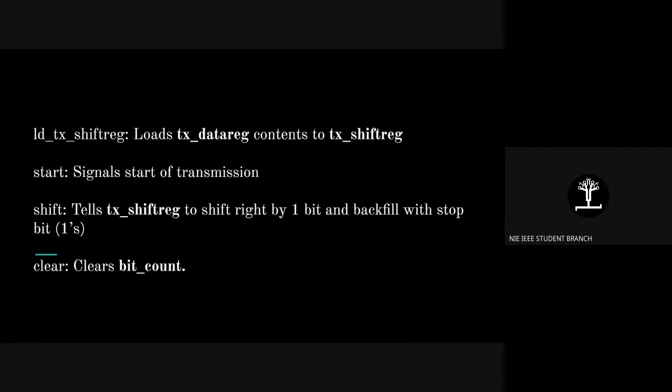LETX shift reg, that is load transmitter's shift register. I just told you that from the data register, you need to put the content onto the shift register so that you can shift all the data onto the serial output, and then that will keep going. So this signal ensures that that happens.